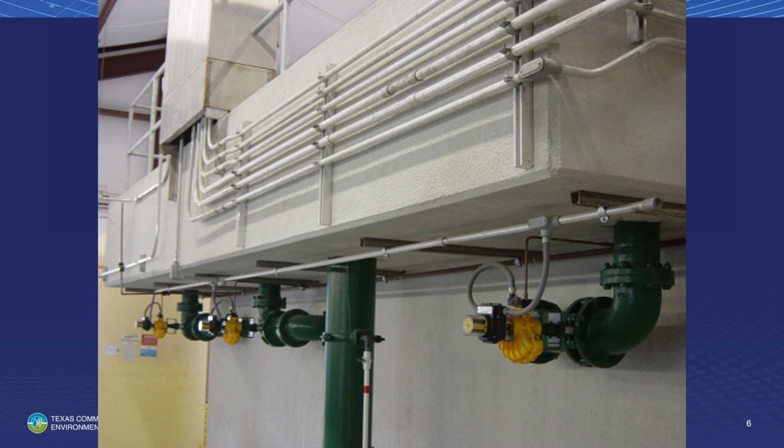And Noble and I were looking at this. There were a whole lot of other issues about this design that we had, but we were looking at this, and the operator was saying, you know, he said, I had to stop feeding caustic. And Noble and I looked at each other, and we looked at him, and we said, yeah? What was the issue? He said, well, you know, my pH on top of filter number 1 was 7.5, 7.6. He said, that's what it's kind of supposed to be. He said, but the pH on filter number 2 was like 7 something.